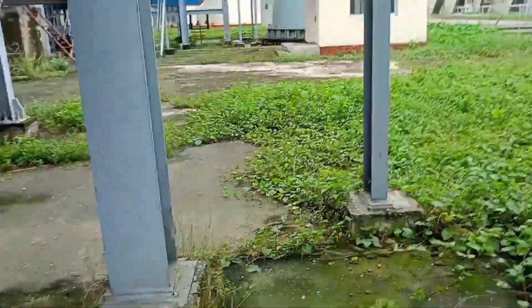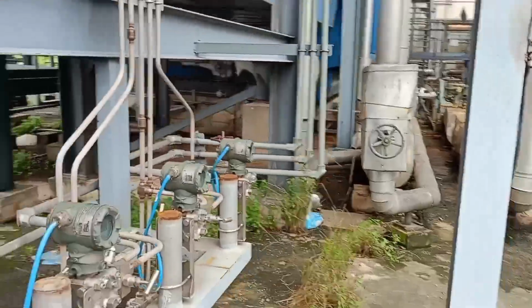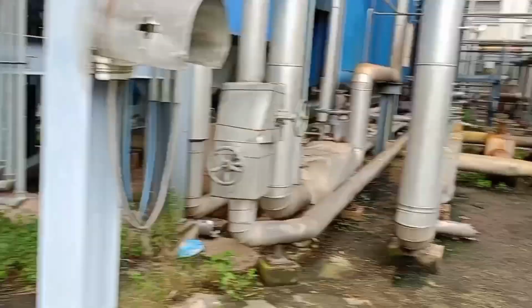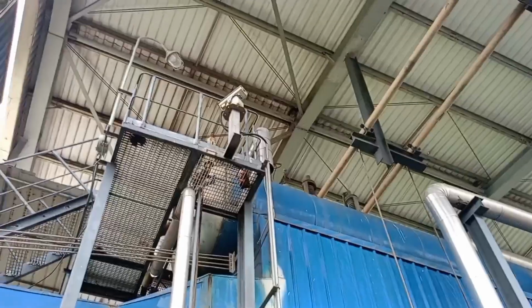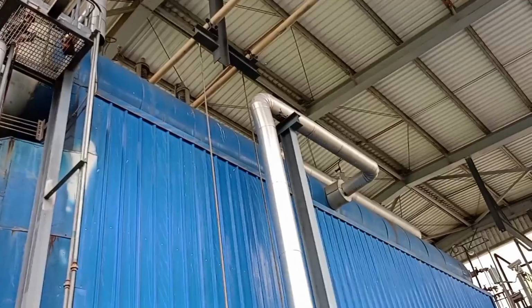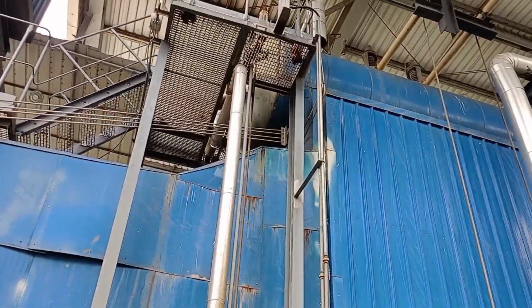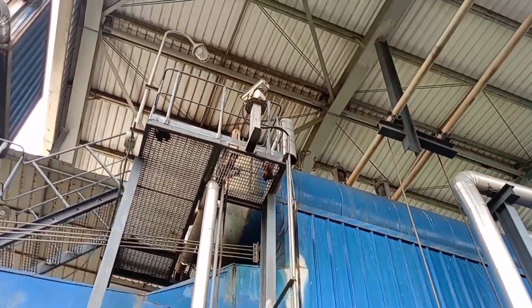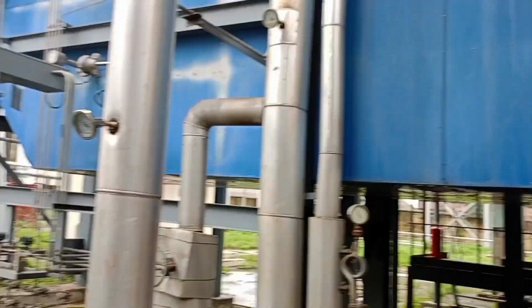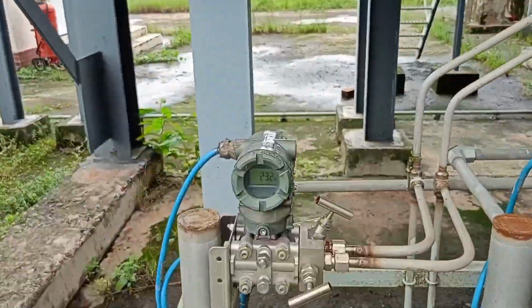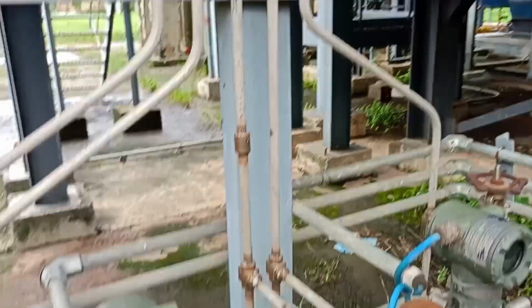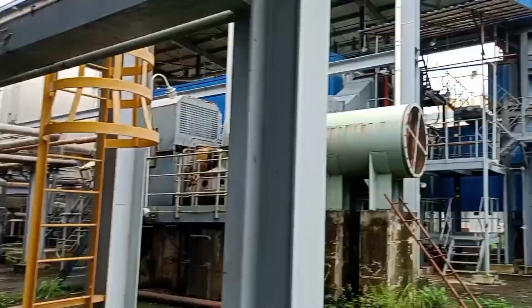You can see here are different transmitters, the level transmitter, pressure transmitter and flow transmitter, and also you can see there are different control valves for feed water, and on the upper side there is a safety valve for pressure regulating or level controlling. Also here is a CCTV camera, and at the same time for level here is a differential pressure transmitter. You see, this is the differential pressure transmitter from the level glass. It is connected. There are 2 boilers.